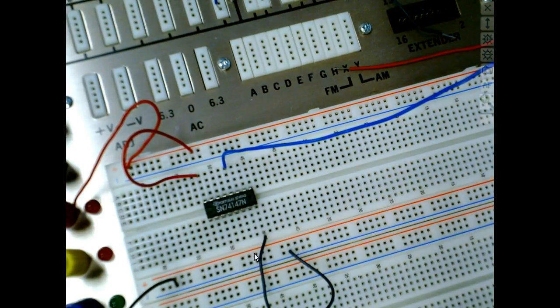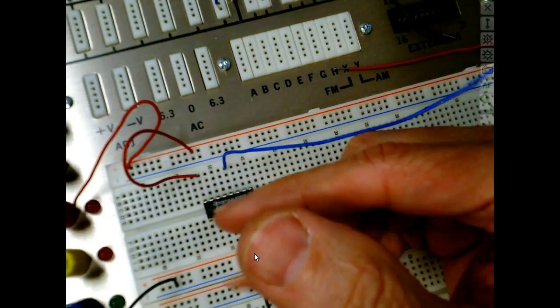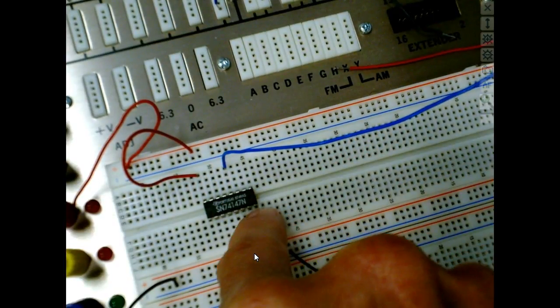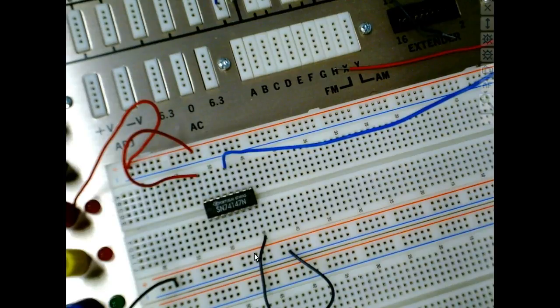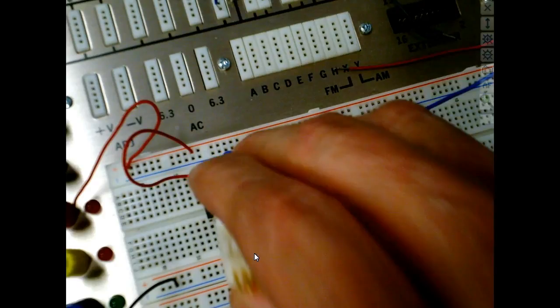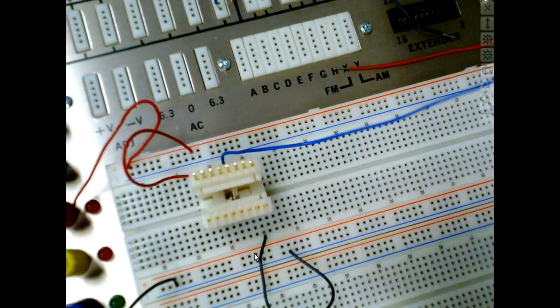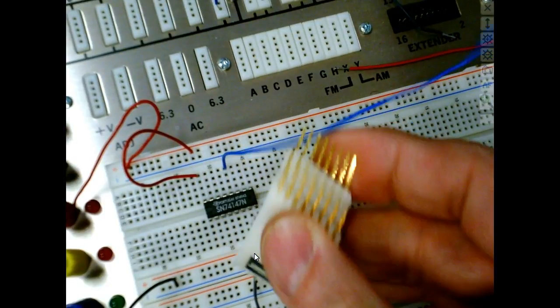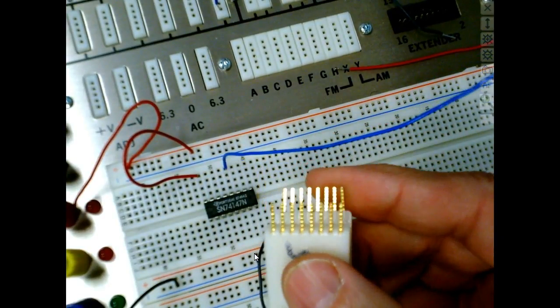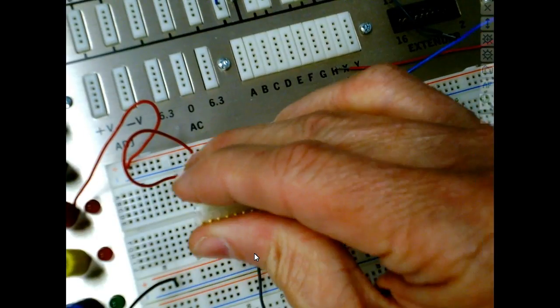And also later on, if we have time, if we hook up a logic analyzer to this thing, then normally what we use are these devices called chip clips. If I'm going to hook a scope up to this thing, normally what we would have to do is pull the tip off the scope, which opens up a ground, and try to get it in there. So normally what we do is we buy these things right here. These are called chip clips. And then we can just clip them onto the chip like that. And now I've got these nice big posts up here that I can hook things up to, right? So these are called chip clips.